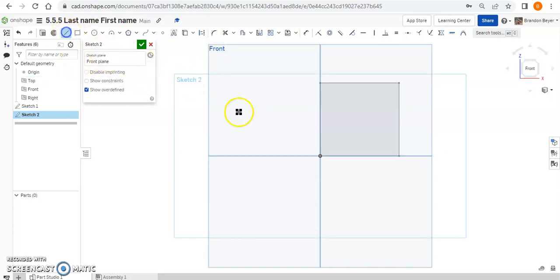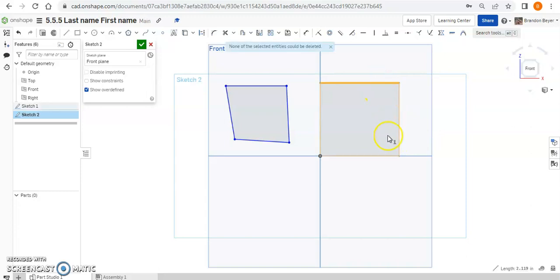There we go. So let's say we're drawing some stuff here, and they're like, oh, well, this is the right box, but I want to delete this one. So they try to grab this, and it won't delete. And they're like, why won't this delete? I don't understand. I'm hitting the delete key, but it won't go away. I can't even select it at all. Reason is, this box is part of Sketch 1, and this box is part of Sketch 2.